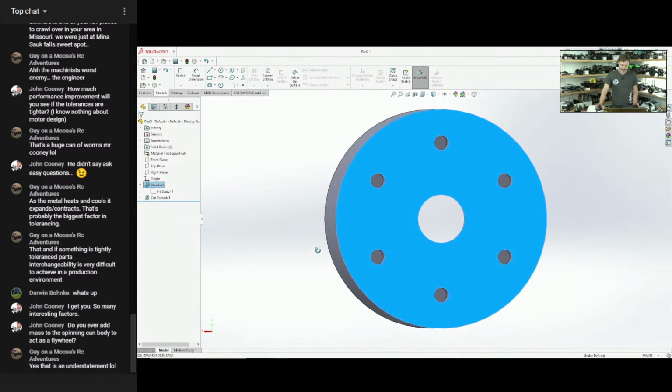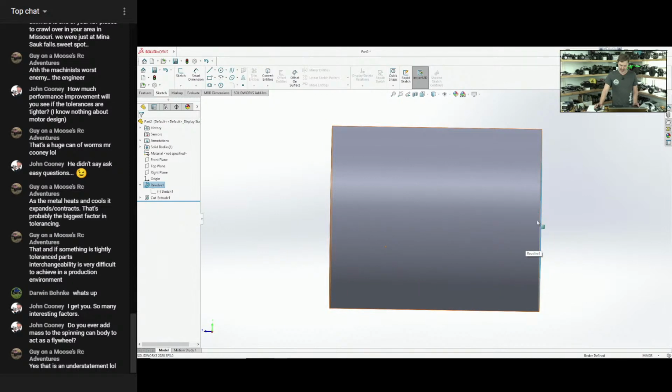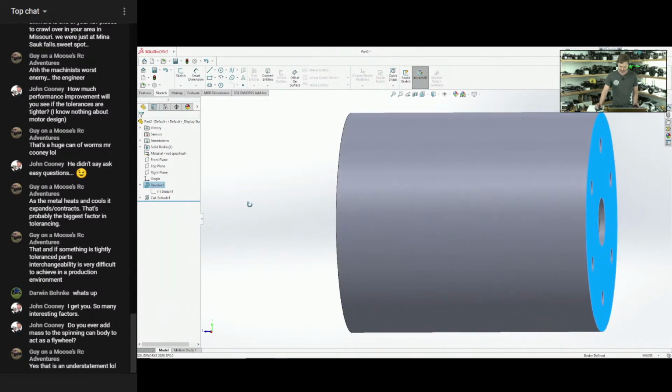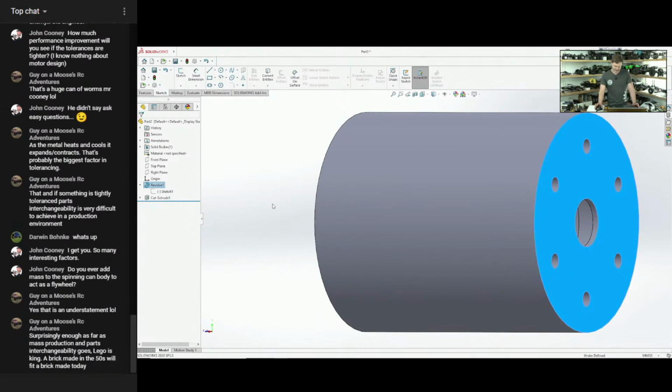play. And when I say radial play, I mean like this. So this would be axial, in and out. This would be radial on a motor. This is a radial flux motor design. So we would have a rotor on the inside, and then we would have our stator on the outside. Really doesn't matter which direction that is, but the flux goes along the radius of the shape of the motor. So a lot of the tolerances on the motor are needed on essentially the radius.